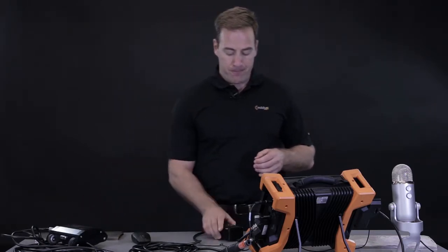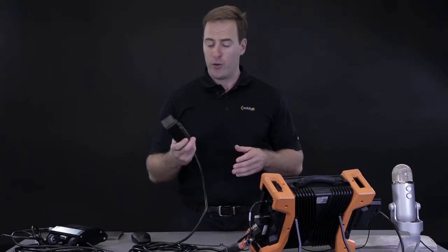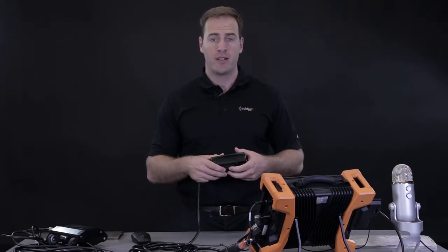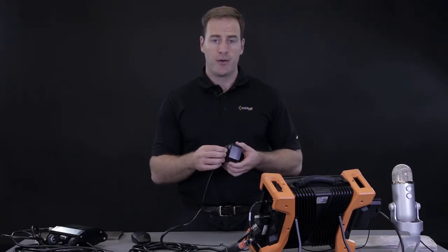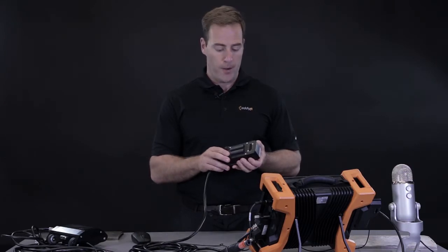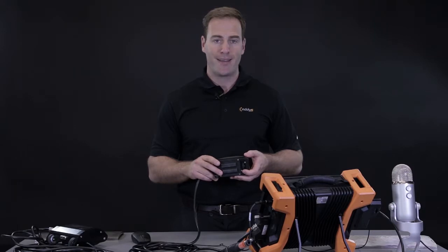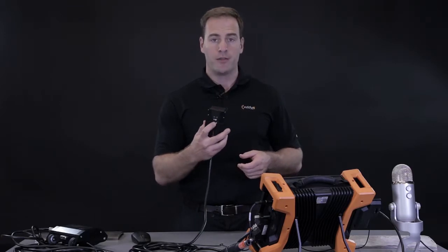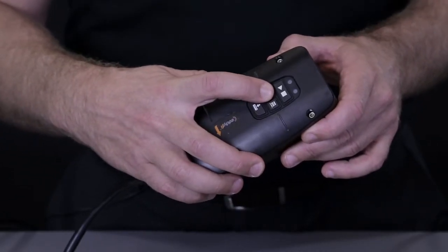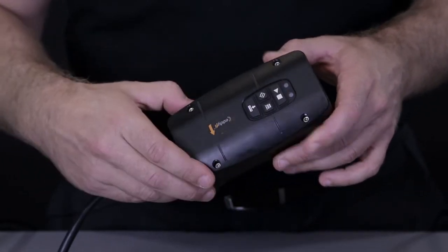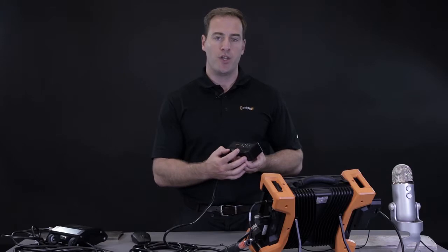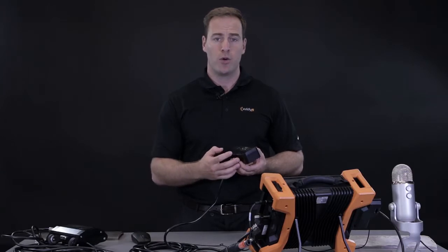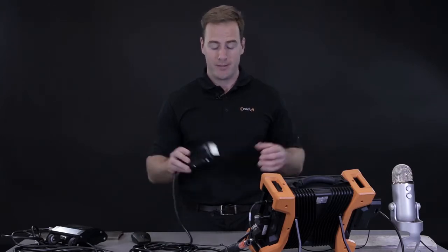So if we get back to this first Sharck probe to begin, in fact, as I explained, this is basically for butt weld inspection. There is an encoder already integrated in the probe. This encoder will help for the defect positioning and for the length sizing. And we have also some buttons on the probe to control the acquisition, the balance, and even the calibration. Basically, this probe has a 2-inch coverage. So during a single scan, we're going to cover the HAZ, the toes, and the crown in only one pass.